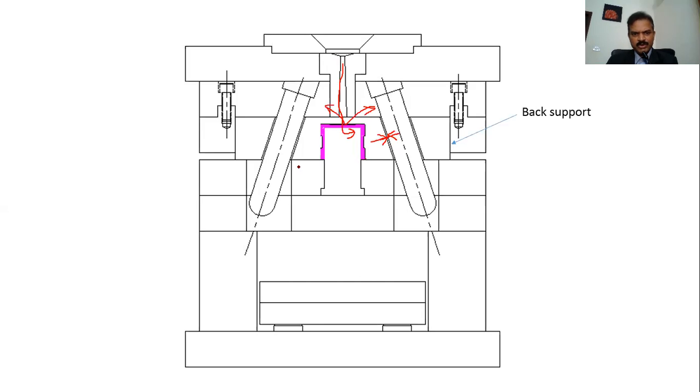Because it will permit a movement of at least the amount the pin is cleared for in the hole, right? So you can't expect the fingers to do the job of clamping the splits tight during injection. Definitely you need a back support.